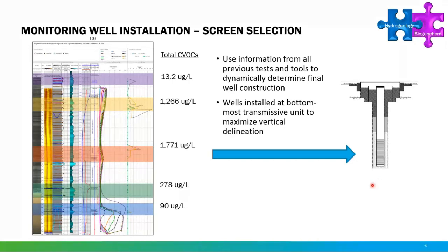It's mostly related to whether or not you're going to have borehole collapse. In that case, you probably do want a monitoring well. In this case, for this site, we were concerned about borehole collapse, so we did install monitoring wells. Ideally, if you have a very nice, competent bedrock with discrete fractures, you can work with open boreholes. That's generally better because you have access right to that fracture in the short term and in the long term.